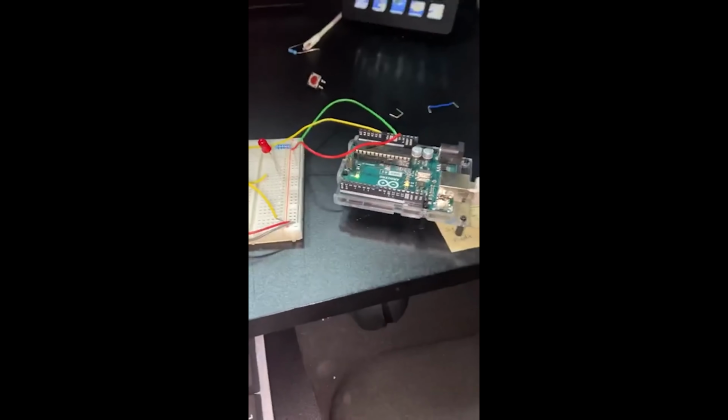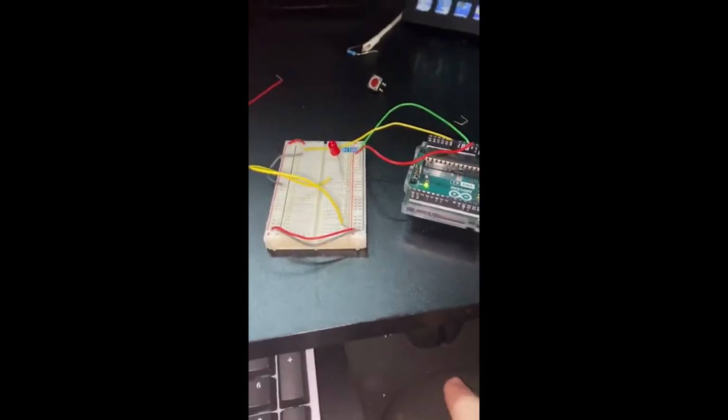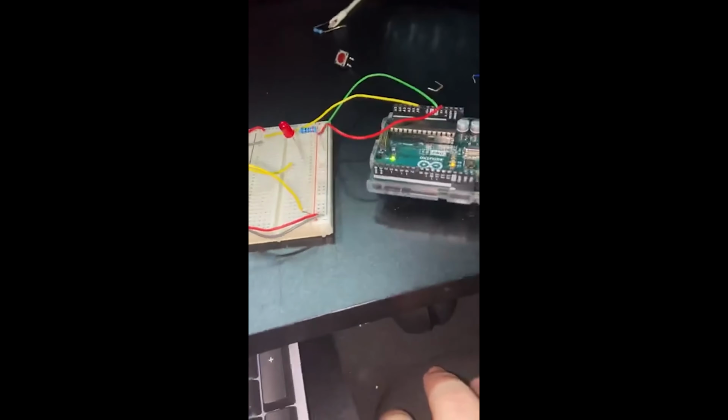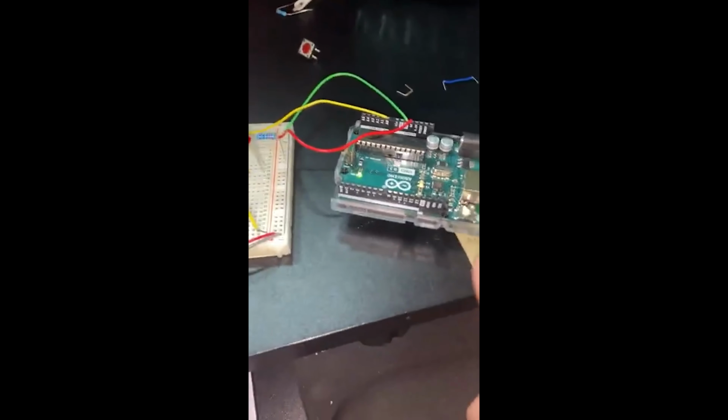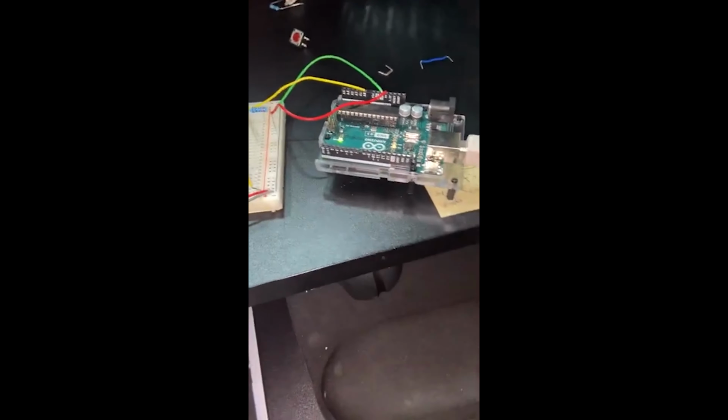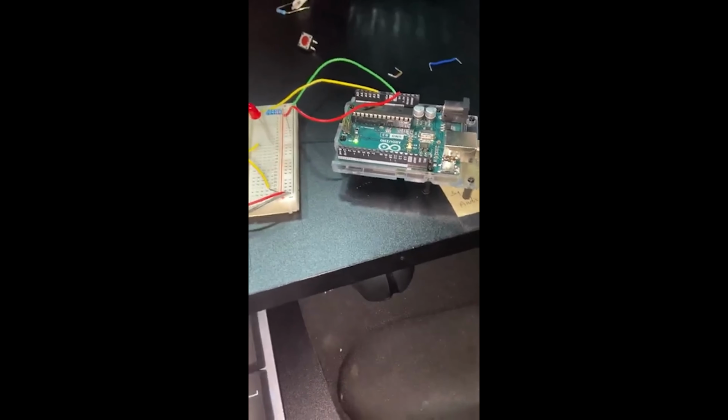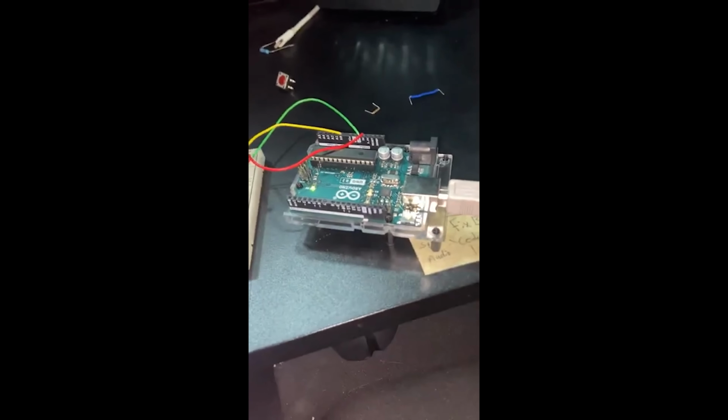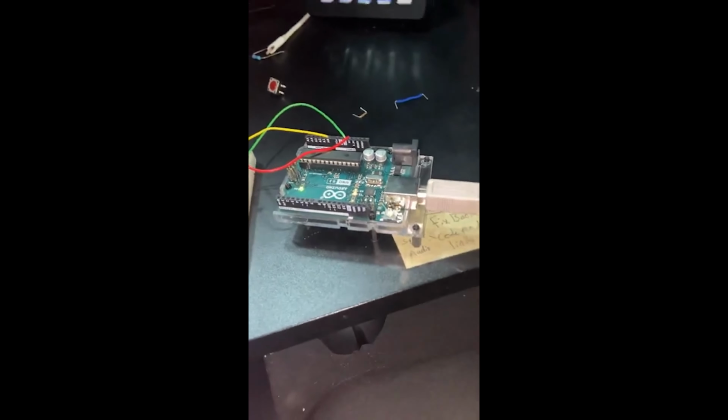The resolution of that, or the amount of those little categories we can put that into, is the bit depth of the computer. If you've ever heard of an 8-bit computer, and things like that, they worked with 8 bits of information, and the more bits you have, the more data. So this particular one here has 1,024 different little categories it can break up that electrical voltage into. And that's kind of the core of the analog signal.